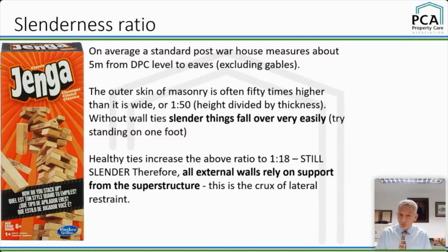So here's the next important point. All external walls, all of them, they rely on support from the superstructure. And that's what we're talking about. That's the crux of lateral restraint, okay? We build a cavity wall out in the middle of the Yorkshire Dales with no walls attached to it, just in the middle of a field. First gust of wind, it'll fall over, okay?